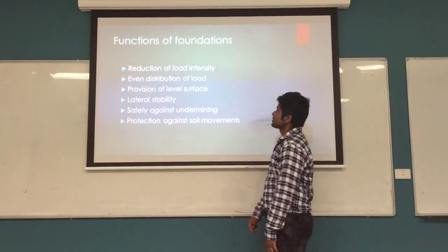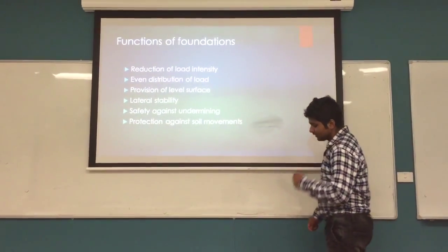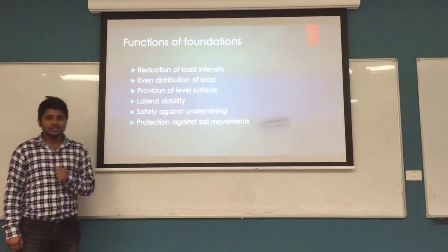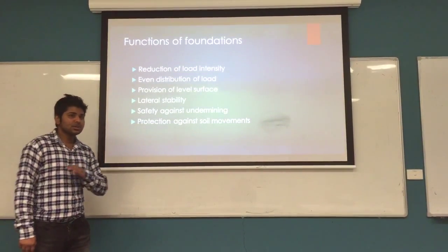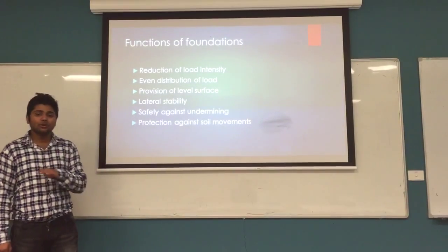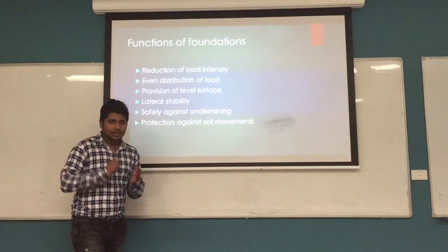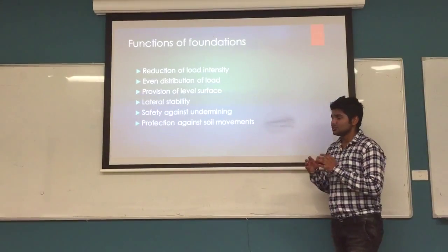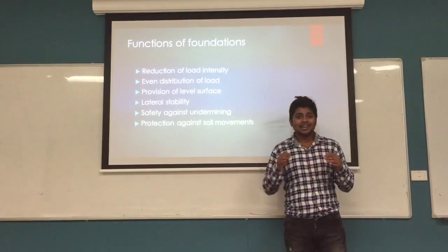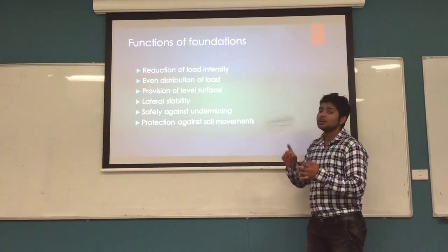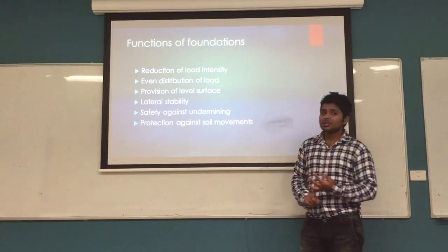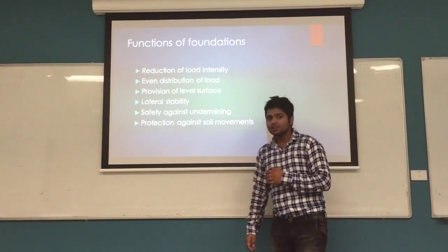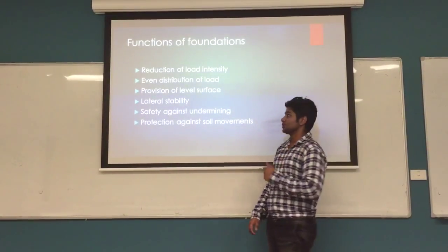Functions of the foundations. There are several functions of the foundations. First of all, it reduces the load intensity of the structure and distributes those intensities equally on the soil. Second, it provides a level surface for the construction of any structure. Besides this, it provides lateral stability, it protects the structures against soil movements, and finally, the foundation provides safety against the undermining effect of water.